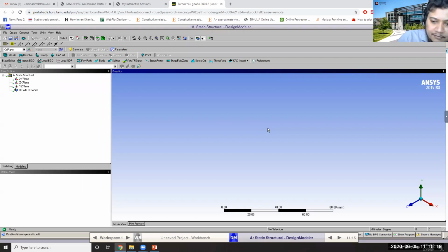For example, you want to create a cube and then make a hole in that cube. You will add the material by creating a rectangle and pulling it in the third direction first. If you want to remove material, you will create the cross section of the shape you want to remove first and then remove the material in the third direction as well. So extrusion works both ways.